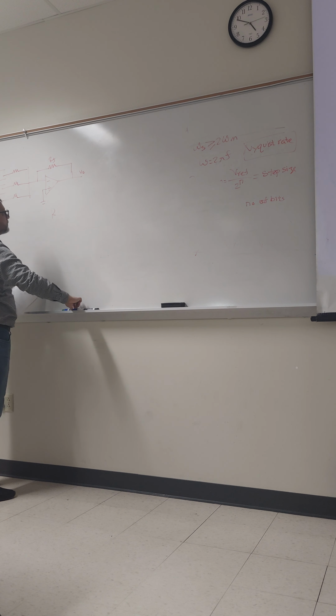In the example, they have given that RF equals R, which means they are equal, both 1 kilo ohm or both 2 kilo ohm. And the reference voltage is also given. So we put the reference voltage 5 volt, and now we take a common 1 over R here. According to the bits 101, it will be 1 plus 0 plus 1 over 4. If you calculate it, you will find V0 equals minus 6.25. I just want to write one more line, then I'm coming to your point. 5 times 5 by 4 equals minus 6.25.